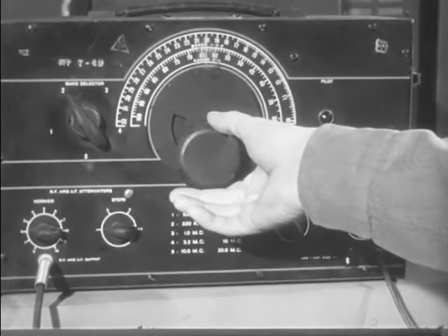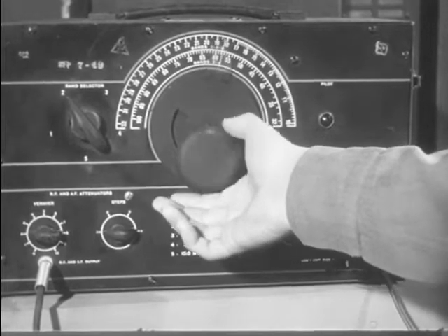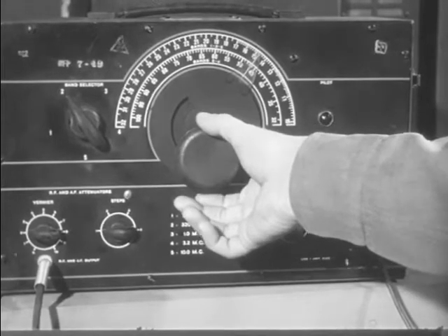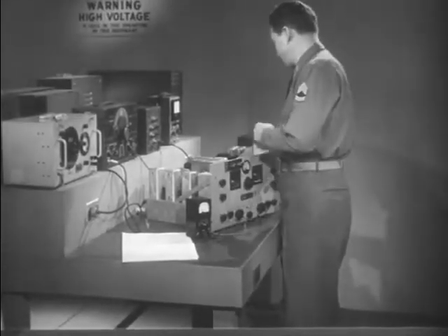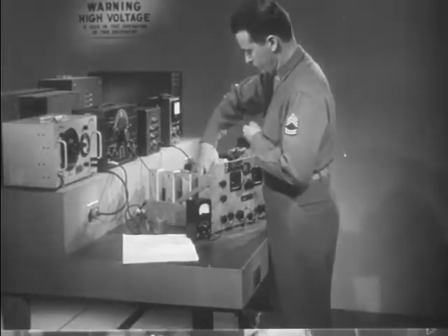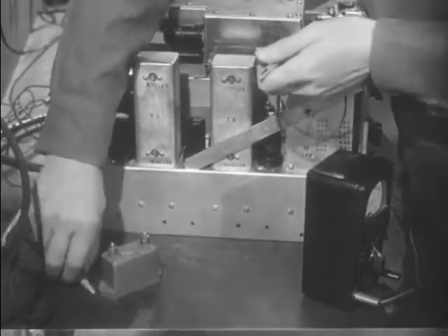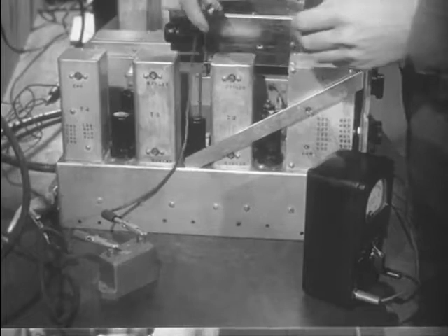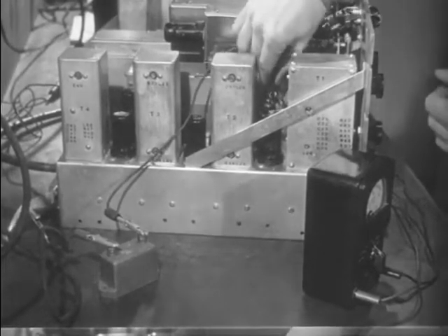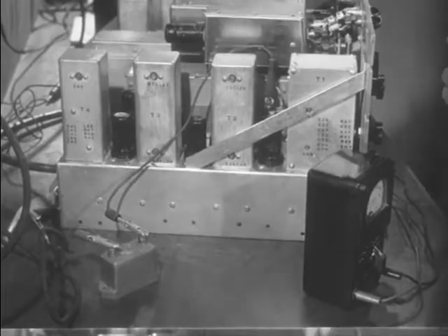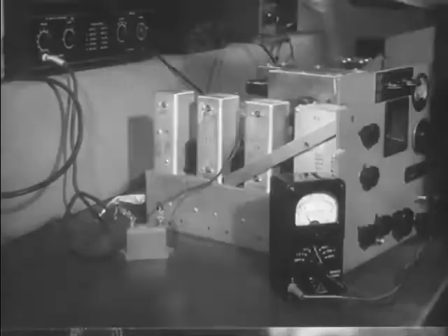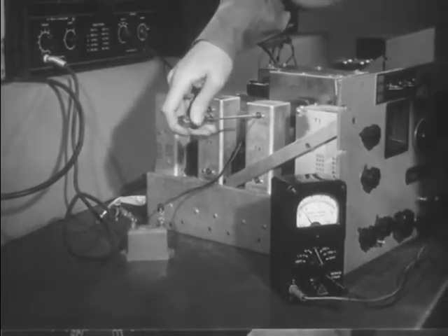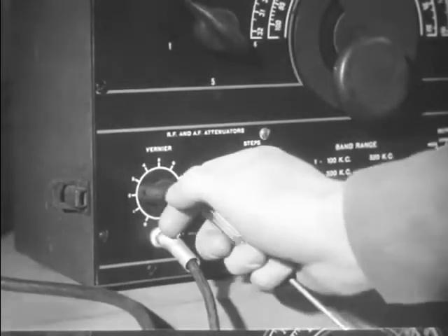We now set the signal generator to this frequency. Then we must connect the signal generator to the input of the first IF stage, since the IF frequency will not pass through the RF amplifier. The IF transformers are adjusted to maximum output indication on the meter. The signal generator output is reduced to prevent overloading the set.